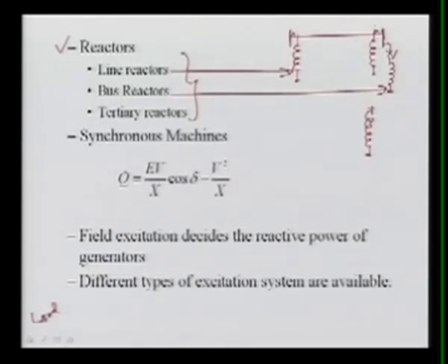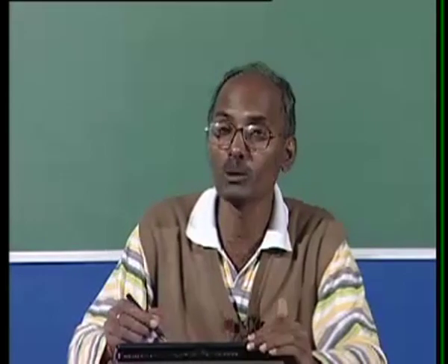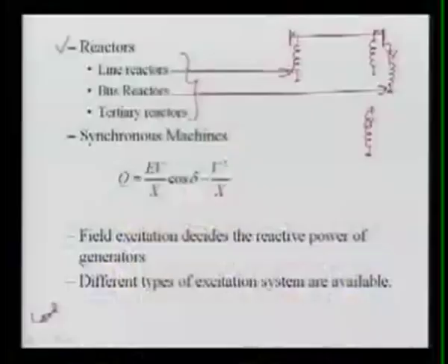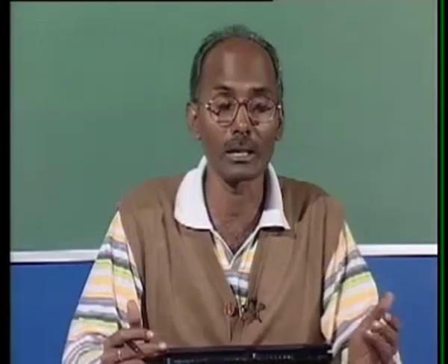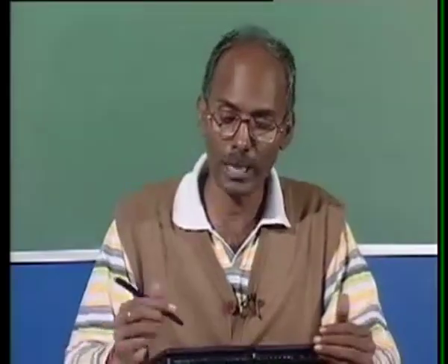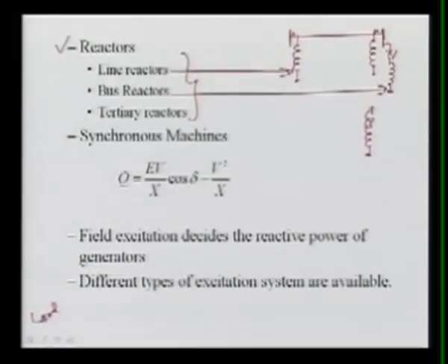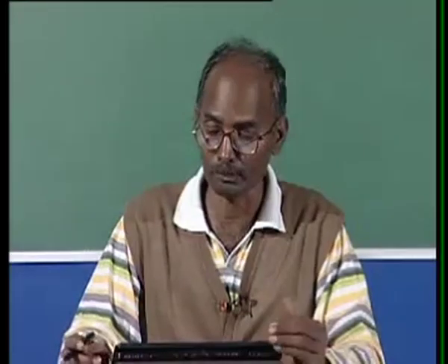you are connecting your line, there is a possibility due to the Ferranti effect that the voltage at the receiving end will be higher than the sending end, and then there will be cascade tripping if we are not reducing the voltage, because the relay will pick up. The overvoltage relay will take care, and then again it will be de-energized. So we have to put all the reactors in the system, then we have to energize the line. We have to connect the line with the synchronous system.